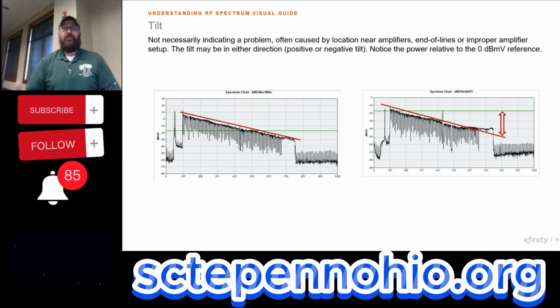Okay, we already referred to compound impairments, right? It's important to understand each of them individually so that when you see them combined, you can start to pull out multiple impairments. Like this first one's a great example. It has a big suck out here right around 350 megahertz or so, and you also have high-end roll-off.